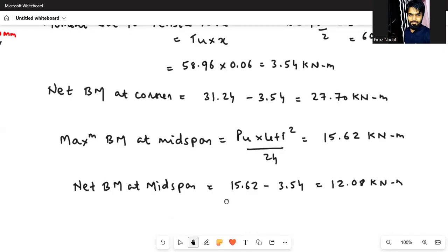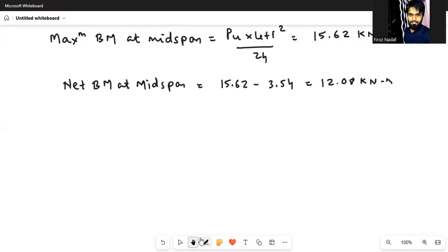Okay, now we know the depth of the wall. Depth of the wall or thickness of the wall is 180 mm. And the wall has to be considered as slab. How you are designing the slab, in the same way wall has to be designed. The wall of the bunker is similar to the design of slab in case of normal building. Okay. So the 180 mm is overall depth of the wall.